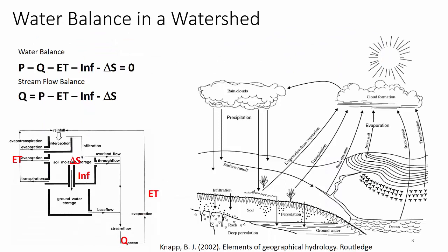Water balance for runoff is simple: precipitation minus evapotranspiration minus infiltration minus change in storage. Think of these as buckets that get filled and take away from Q. Everything dies, all water evaporates. Those are some of the foundational rules.